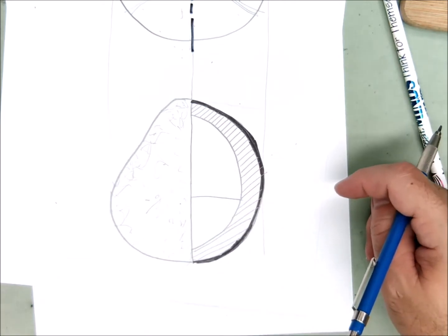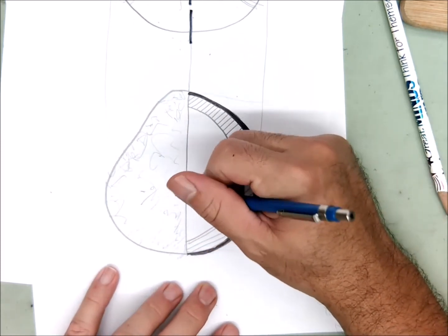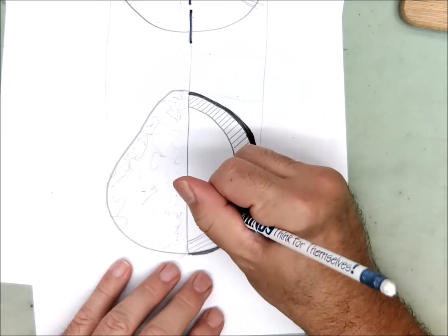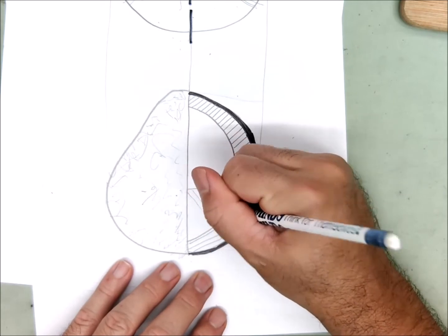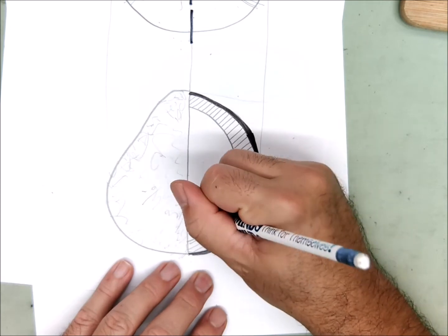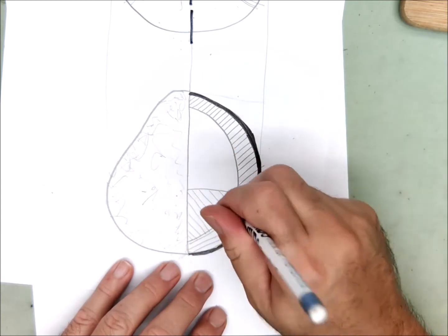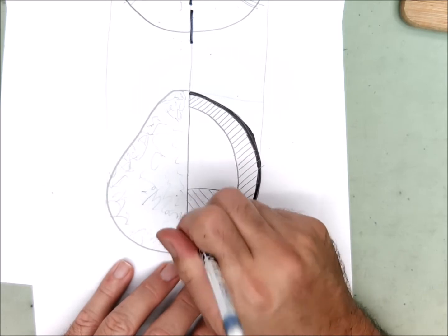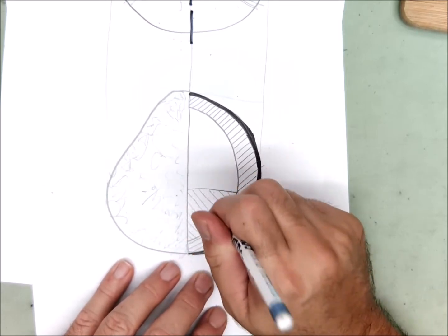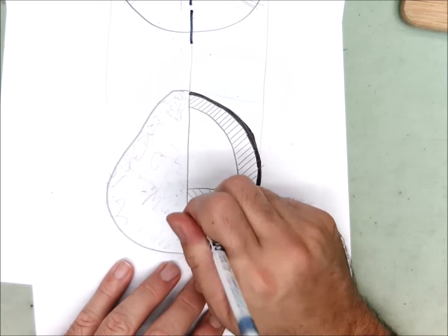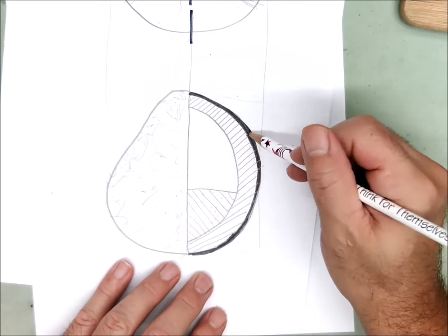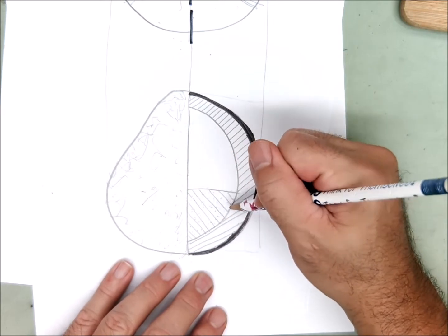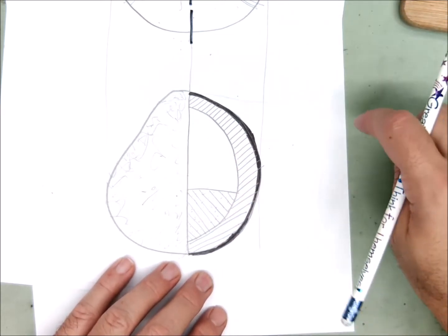Now the liquid is a separate material, and there's nothing wrong with doing your 45-degree lines in the opposite direction, but you know, there's a bunch of different patterns that are used to indicate solid material. And sometimes it's 45-degree lines, sometimes it's 45-degree lines in both directions. It might be small dots, stippling, it might be shaded in with a different tone, maybe like a light gray. It could be lines, but a pattern line, like little dashes instead of continuous lines. Right, there's a bunch of different ways to show that this and this are two different materials.